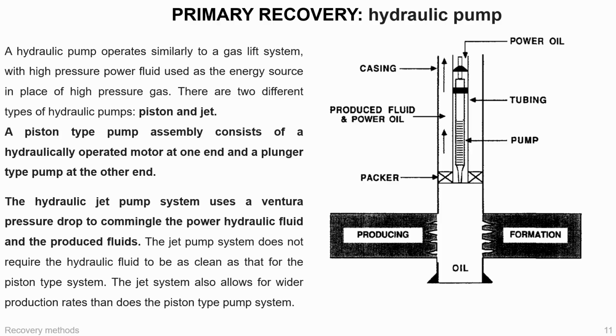One advantage of hydraulic pumping is operational flexibility. Jet pumps, in particular, can handle wider production ranges and may be less sensitive to solids than some other systems. However, hydraulic systems require surface fluid circulation and proper fluid handling, which can add complexity.